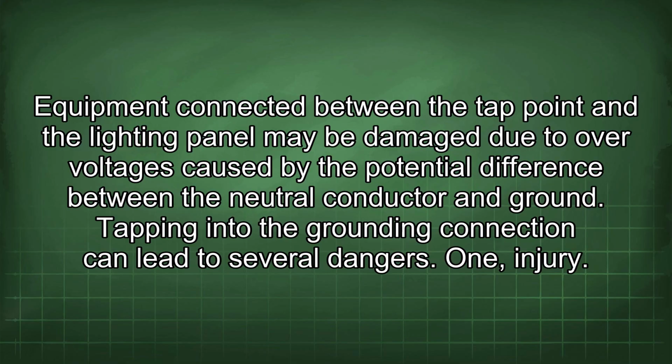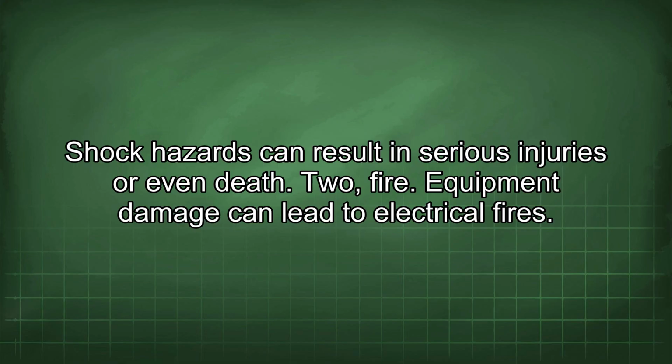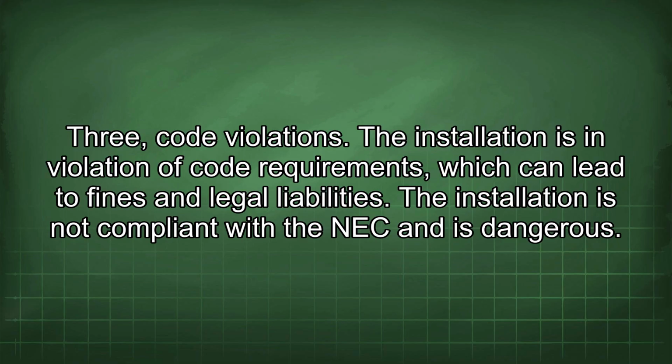Tapping into the grounding connection can lead to several dangers. 1. Injury. Shock hazards can result in serious injuries or even death. 2. Fire. Equipment damage can lead to electrical fires. 3. Code violations. The installation is in violation of code requirements, which can lead to fines and legal liabilities. The installation is not compliant with the NEC and is dangerous.